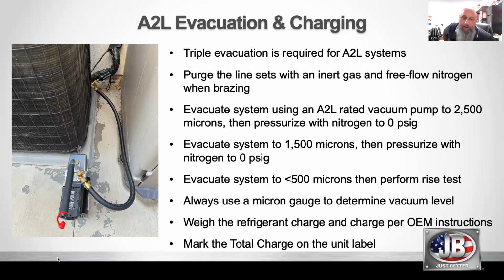Yeah, just real quick on that, Tom. Just for folks who don't know, a 1/4-inch hose will only do about 1 CFM. So if you're running a 6 or 7 CFM pump on 1/4-inch hoses, you've got way more pump than you need.